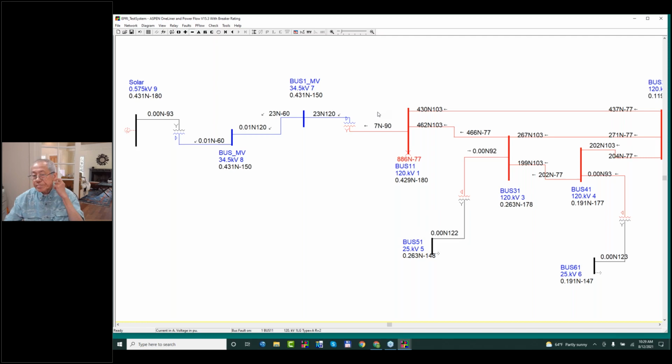Now, why the two lines? Given what I just showed you, it has no negative sequence and no zero sequence, and there's only positive sequence output from this generator, no matter what. That's the state of these things now. So why would the two-line to ground fault and the two-line to line fault be different? Well, that's because the output of this thing is based on the positive sequence voltage. So if I look at the positive sequence voltage, right now it's at 0.66. Now if I put a two-line to ground fault here, and a two-line fault without the ground, you're going to see two different numbers over here, right? And so that's why the outputs in those two cases are different. Does that make any sense?